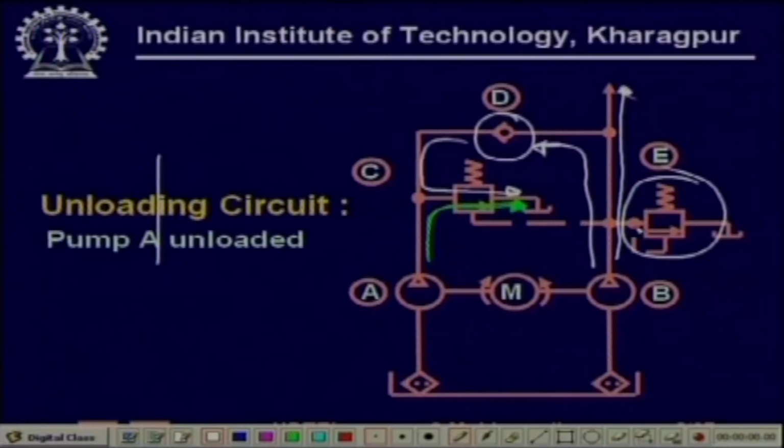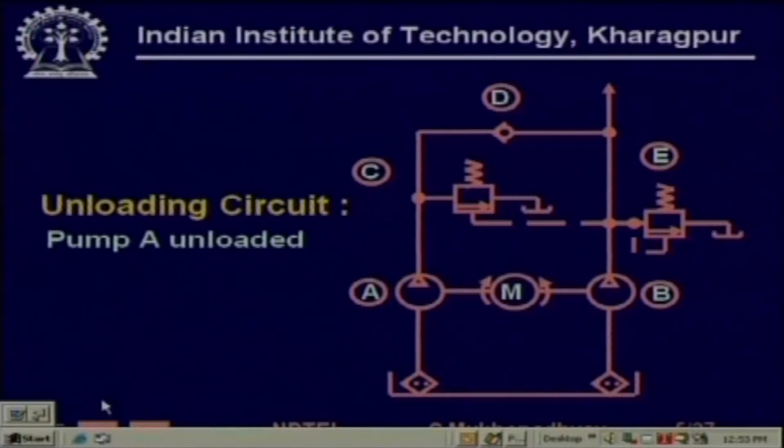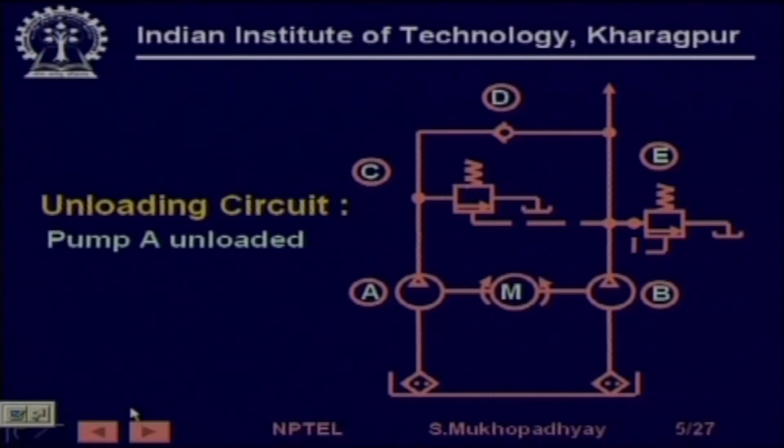You see, all pumps have overload protection using relief valves. So, if for some reason you have put such a heavy load which cannot even be handled by one pump, in that case this relief valve will vent and the load will of course stop and the fluid will flow like this, but the motor will be protected from overloading. So, this is the way this circuit functions. Then we go to our next circuit. We are going to see a number of such applications.